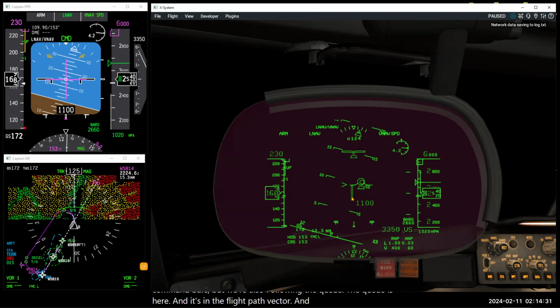And this long column is indicating that it's a speed error tape, but as I mentioned in many of my videos, it's also a speed differential tape, meaning indicating our speed is an error on the low side. Well, if you look at the actual bug setting, we're in VNAV speed, and the bug is at around 230 knots.